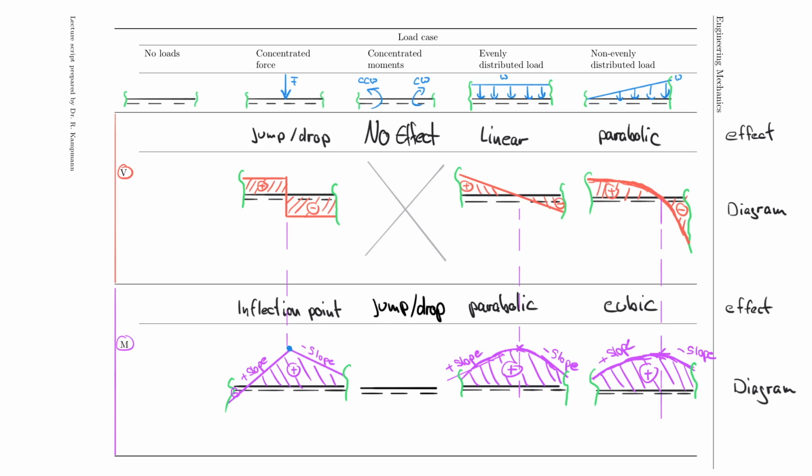And so what you will find is actually that you have a clockwise or counterclockwise jump. And let's think about what that means. So this is turning counterclockwise, this is turning clockwise. If I now were to cut the system here and I come from the right side, so I release the entire system and bring in my internal force at that location, let's say this M here, so you can see that that would actually put the counterclockwise into balance. So the jump here, due to this force, would make it more positive because they are already acting against each other.